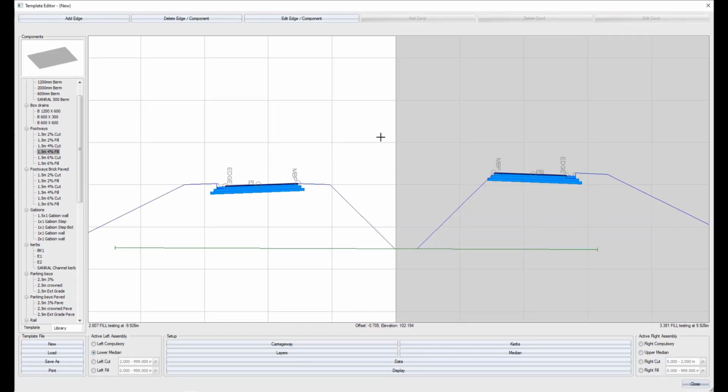Another very nice function is to have the option of right-clicking and exporting the template to a drawing. In that case, Civil Designer would create a CAD drawing at the drawing scale of choice. Civil Designer would also insert and populate a pavement layer table. In a similar manner, we also have the option of importing drawing information and applying it to the template.